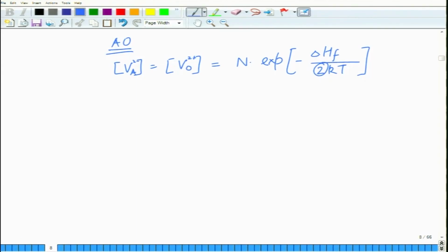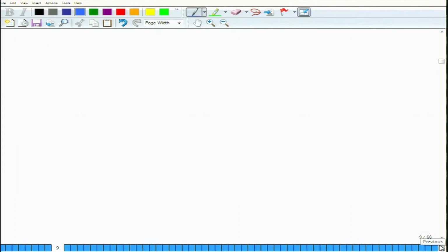So, this is about the point defects discussion, that you have point defects such as vacancies and interstitials, and point defects are basically stable defects, they are equilibrium defects, and free energy is minimum at a certain concentration at a given temperature, and their concentration increases as a function of temperature. So, as you increase the temperature, they become more in number exponentially. Okay. So, now let us discuss the second category of defects, which is called line defects.